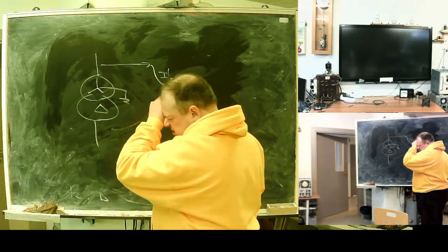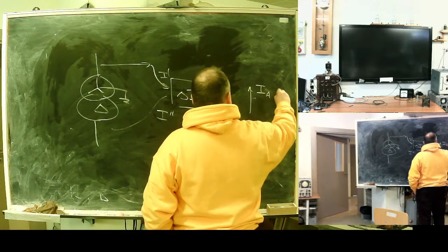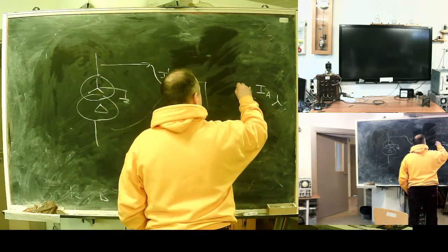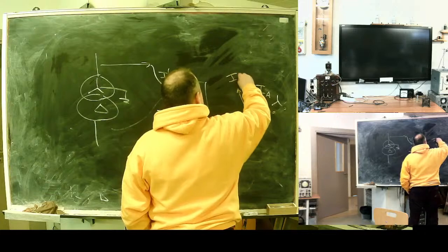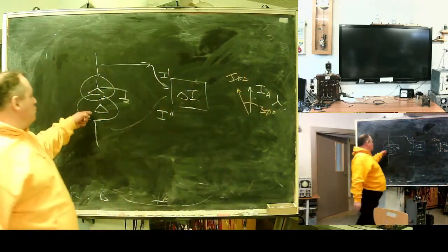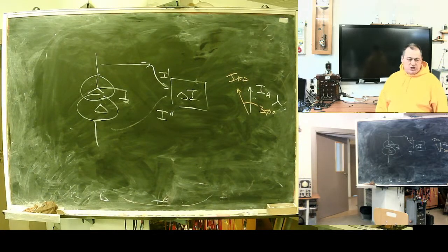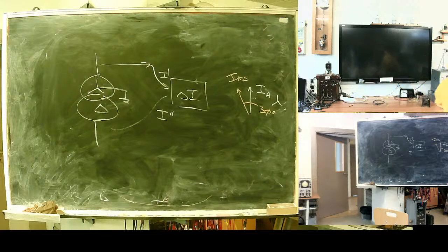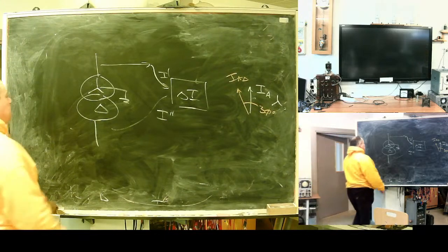It will be something like this. A phase at a star, if it's European, you will have 30 degrees here. It's a delta. Because it's a delta star transformer. You will see a 30-degree shift. And this shift limits the sensitivity of your protection. It's a problem. Old way to solve this problem is offset current transformer connection.